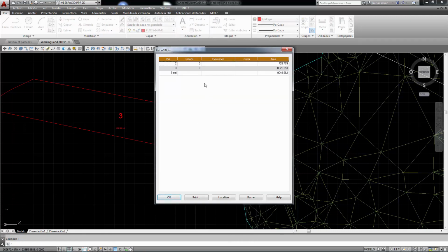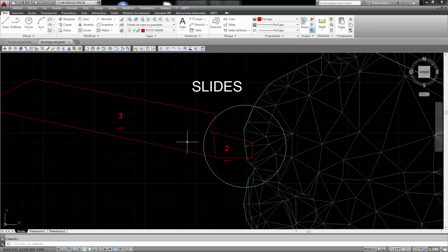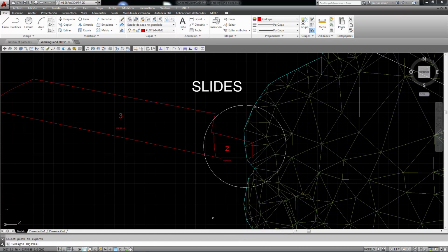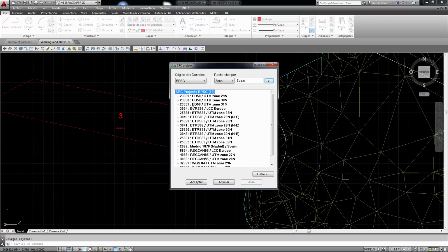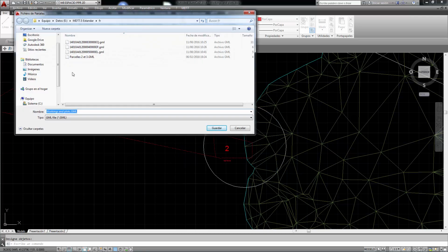Well, our works management or technical office can prepare a plan for the property. The plot tools feature a complementary tool to help us in the representation of this division, for example. So as not to overload this sketch, we can go MDT, Plots, Export the GML. Why? Because we can validate this land registry division in order to facilitate customer and owner management by selecting the objects we wish to export, which in this case is the division. We then right-click, assign a location, and accept.